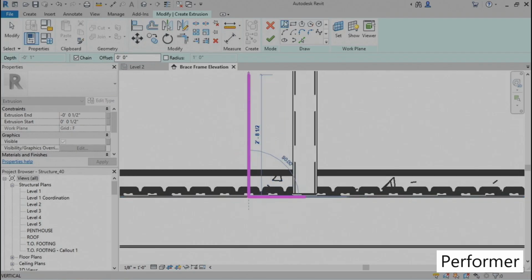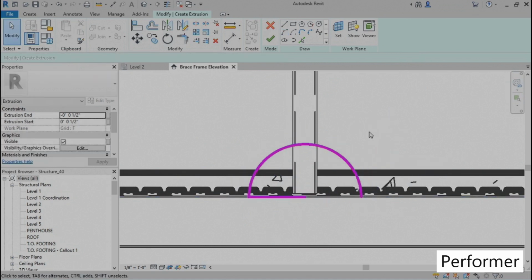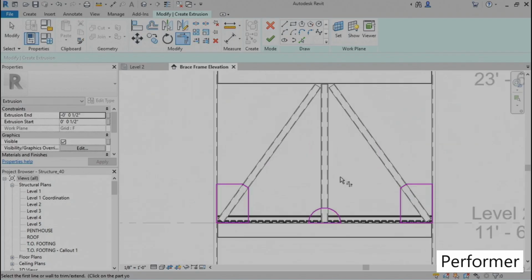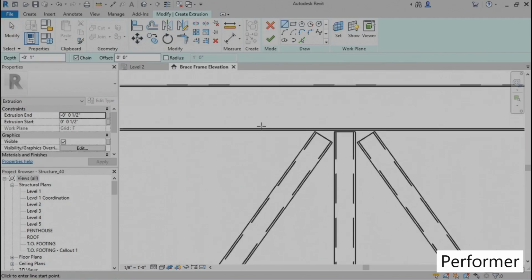Now, click the arc button. Come all the way over 2 foot 4. Pick a point there. Now come straight up. Pick a point there and escape a couple times. Say TR for trim. We are getting fancy. All right. Now let's just do one up here. This won't be that fancy. Click the line button. Pick a point here. Corner 2 foot 2. Come straight down to here. Geez, that's pretty long. So 2 foot 2.